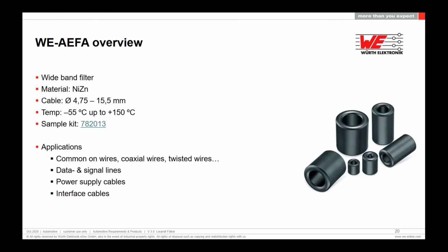There are different manufacturing processes. Nickel zinc ferrites are sintered ferrites. You take the different oxides, press them together, put them in the oven, and bake them for 16 to 19 hours, and you have a very good, reliable ferrite up to 150 degrees Celsius with a non-conductive surface. You don't need to coat them. Exceptional for EMI for several hundred megahertz. You can use that for EMI problems.